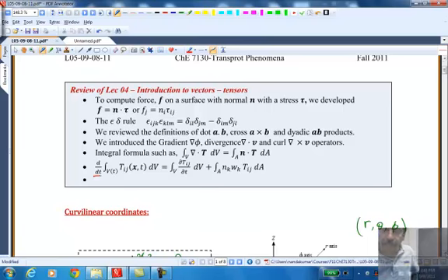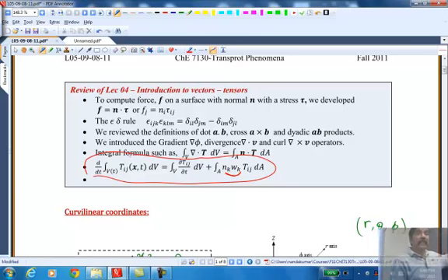Okay, here. This is essentially the result that I'm talking about. d/dt of any quantity over the volume is equal to the integral of the rate of change of that quantity with respect to time plus the normal component of the surface velocity multiplied by the same quantity. This is the Reynolds Transport theorem.